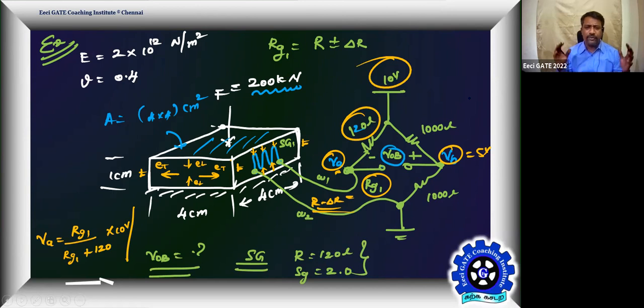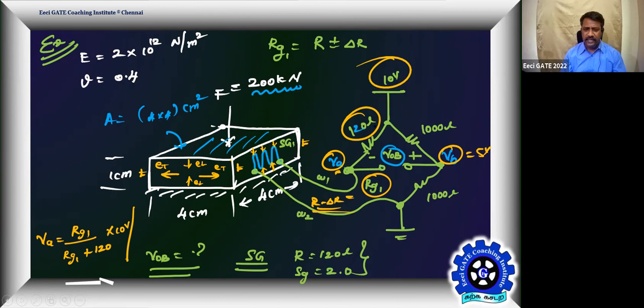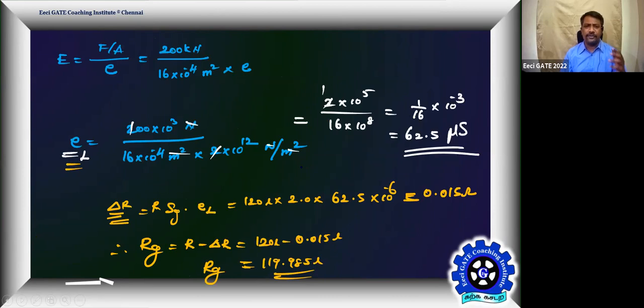Now I have shown you a complete setup of strain measurement. Only the signal conditioning part alone is not given. So you know how to do the signal conditioning for this. Clear? Yes, sir. Okay, that's a complete setup for force measurement. Understood the load cell, how it is converting the force into strain. A lot of mechanical parameters we played, we established good connection, and finally we play with the strain sensor.